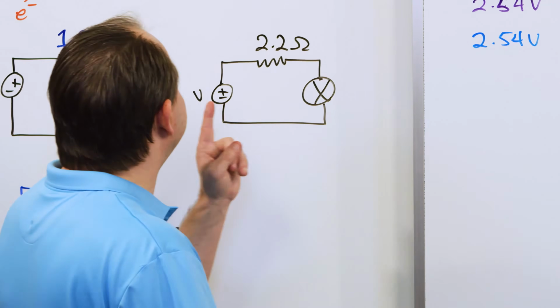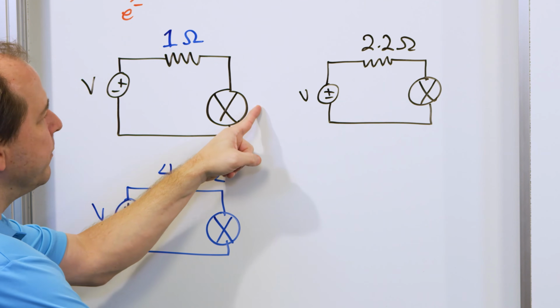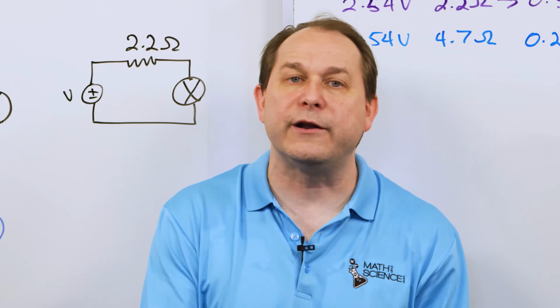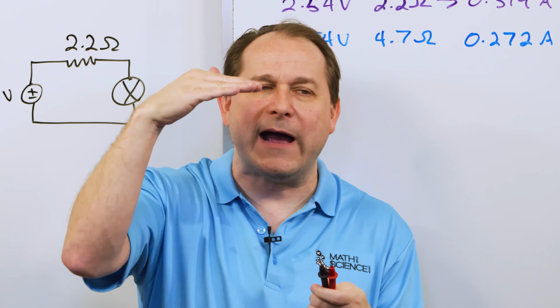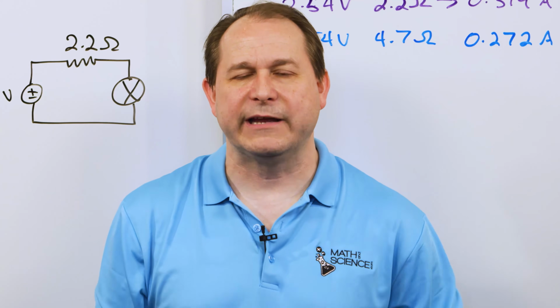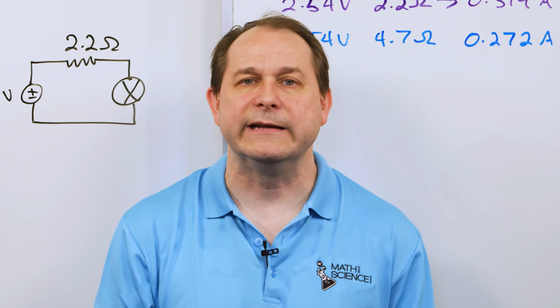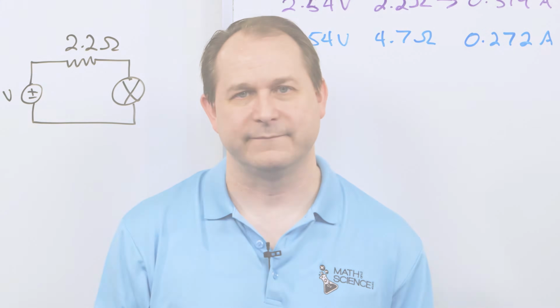So in our first circuit here, we inserted a 1 ohm resistance. This thing almost has 1 ohm in each of these positions. So when we calculate the current using Ohm's law later, you have to use the resistance of everything in the loop. And that's why when we doubled the resistance, we didn't quite halve the current. But we will do those calculations later to show you that Ohm's law, which we will learn in a later lesson, works for any branch of any part of a circuit.